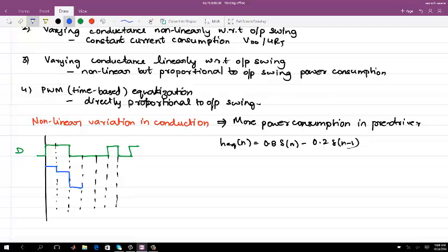Then for the minus 1, you will again have minus 0.6, minus 0.6, and then you go to plus 1. You got this, right? This is the equalizer output, meaning this should be the output coming out of the output driver. So this is voltage mode equalization.